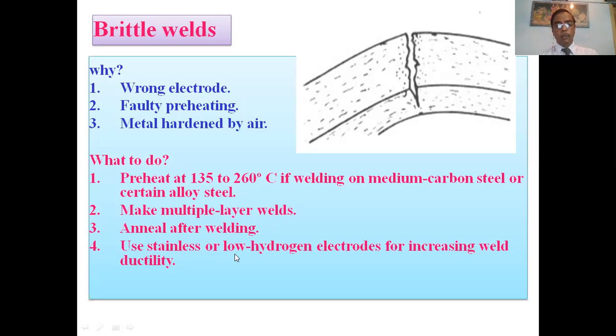Use stainless steel or low hydrogen electrodes for increasing weld ductility. That has to be taken care of for proper use of the welding.